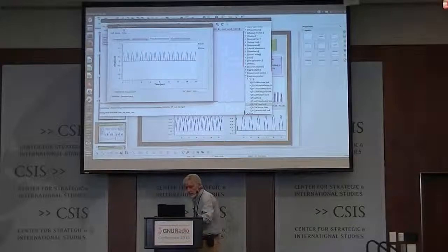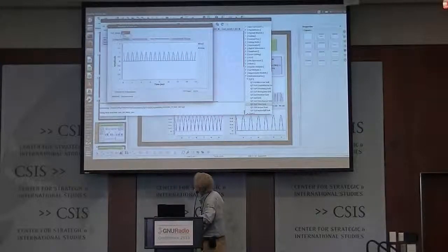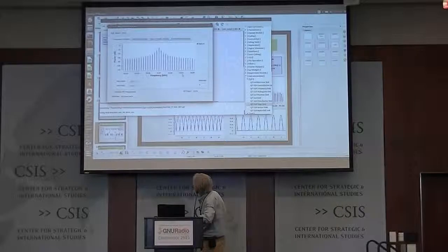That's a pretty basic component, of course, for electrical engineering. But the interesting thing now is, I'm going to put this back to full wave. You get this picture here in the frequency domain: the DC component is here, the fundamental frequency is here, and the second harmonic, third harmonic, and so forth.